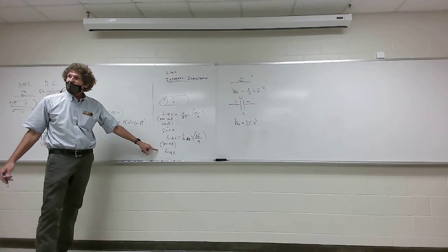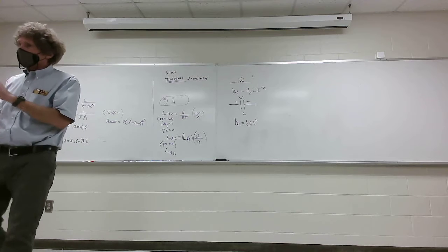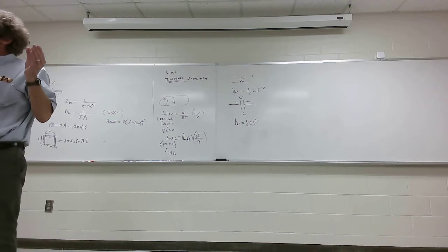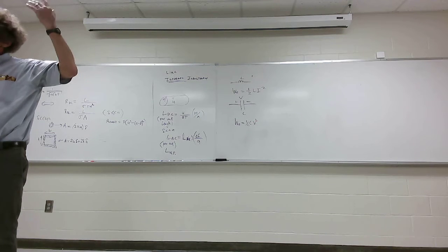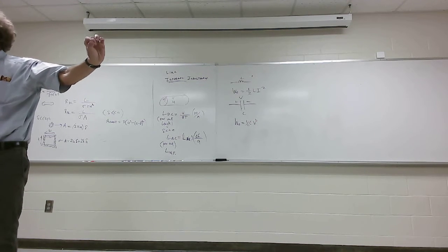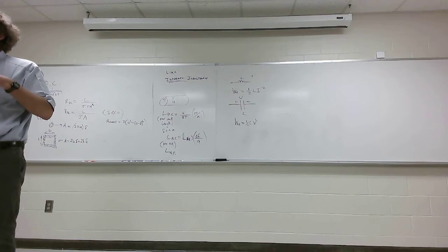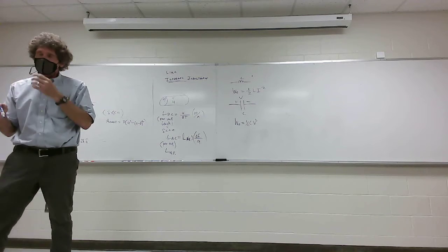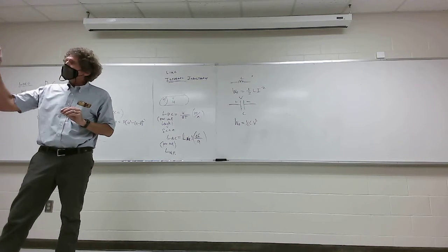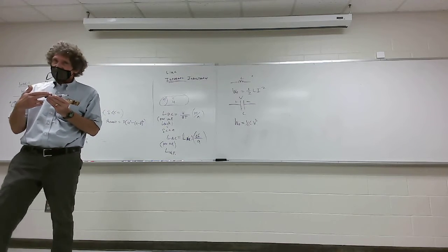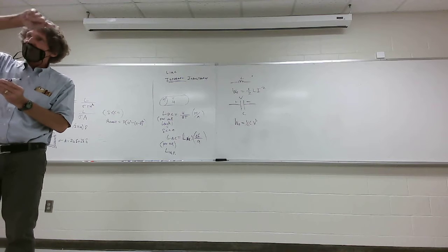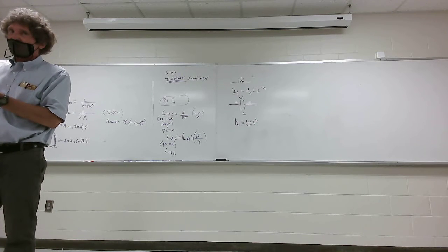You all hear me? Now, something he doesn't get into in the book: wouldn't you think most of the energy in the magnetic field is outside the wire? Doesn't that at least make intuitive sense? Well, it is. But they can't talk about a general formula. He has one called partial inductance, and here's why. The only way you'll find out the amount of energy associated with a given current element is to know how the return current gets back to the source.